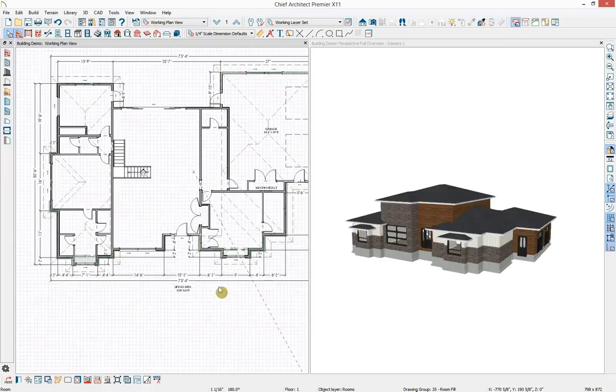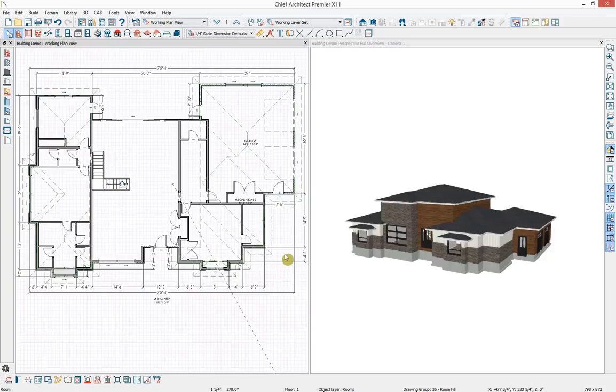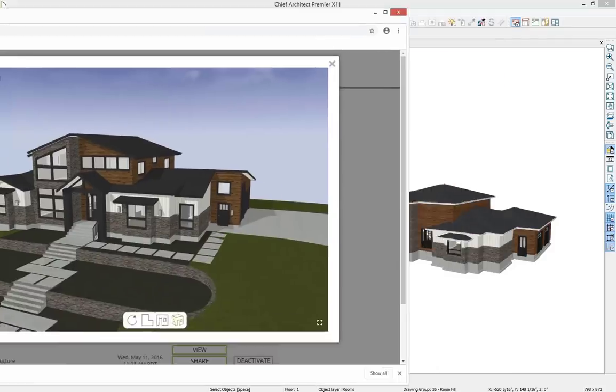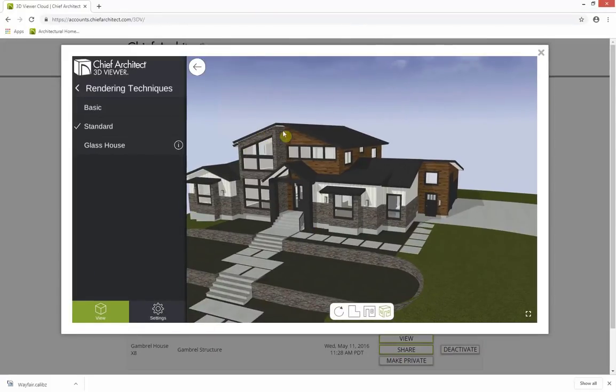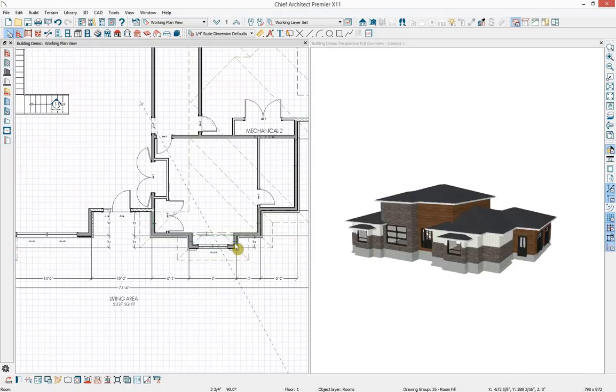So the other way that we're going to affect the roof planes is by opening up the walls and telling the roof plane above it how it's going to function. If we take another look at the full home, you can see these walls need to be gables. We have a gable here and here as well, and then we also have a gable in this section. And changing a roof to a gable roof essentially just means that there's not a roof plane bearing on it. So we also are going to change the two edges on each of our bump outs to gables, which is going to make them effectively shed roofs. So let's start with those.